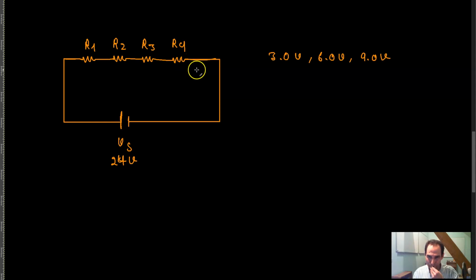But then you need to make sure that the resistors you put together draw some current from your power supply, and that current has to be accounted for and allowed in the circuit, meaning your power supply has to be able to actually deliver that current.